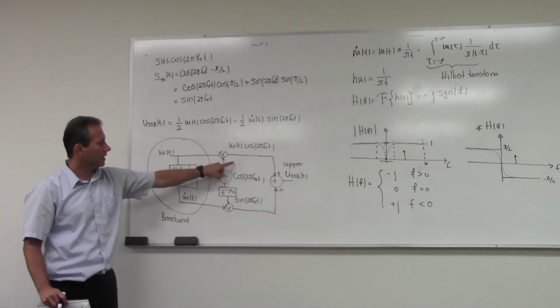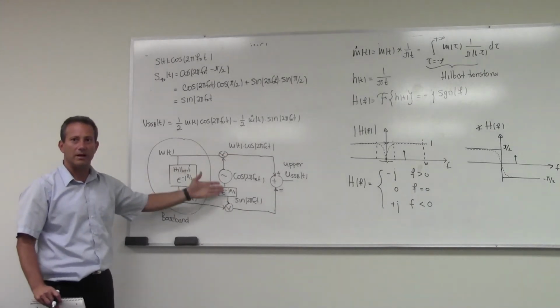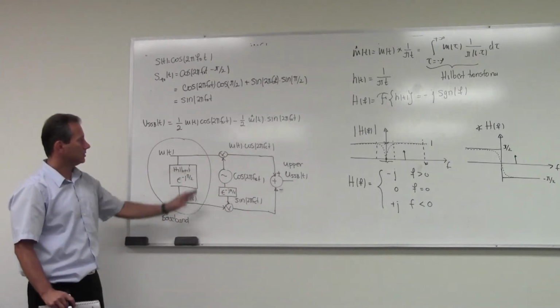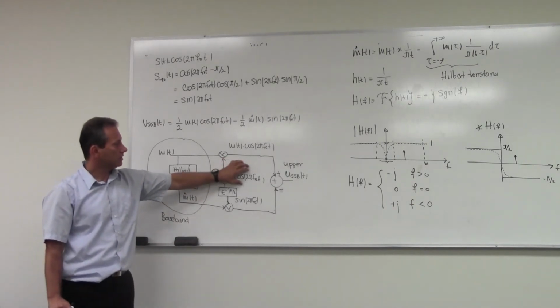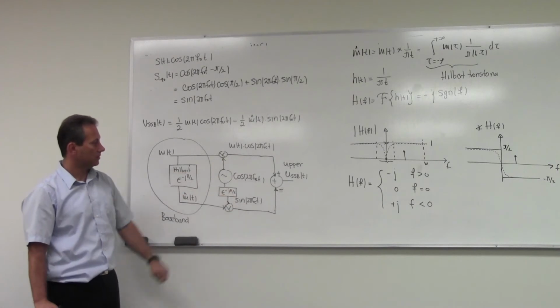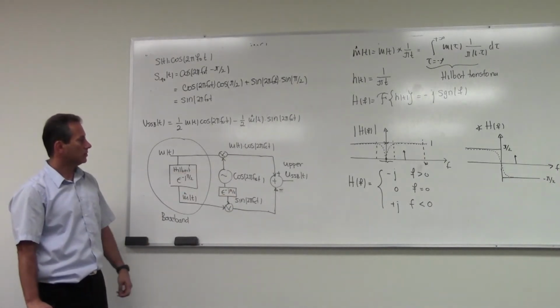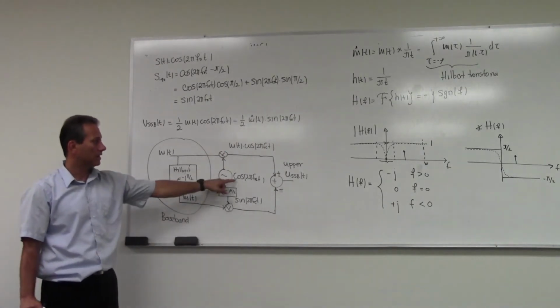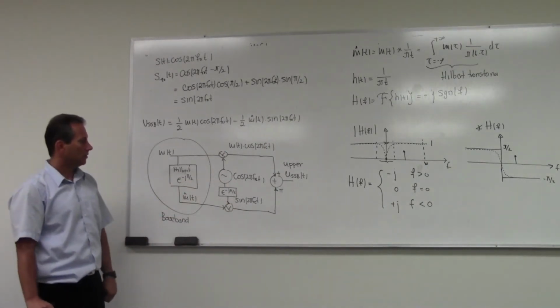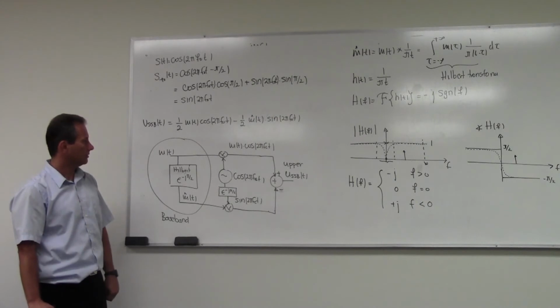We call this component I and we call this Q, and this is a balanced I and Q modulator. So this is very common, where you don't use a single cosine, but rather cosine and sine in pair. A lot of modulators come with this circuitry built in, where you have a carrier and its quadrature already available on the very chip.